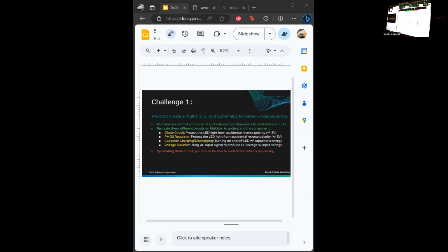Is there a specific reason why anyone would build a circuit to run reverse polarity, like when you want to put in negative? So yeah, in an op amp, for example. An op amp looks like this, right? Where you have 2 inputs and an output. Some of them you can power up like this to ground, and this one to VCC. But actually, some of them, depending on the data sheet, you have to have negative VCC for it to power on. So you need both the plus and the negative. That's one example of why you might need it.